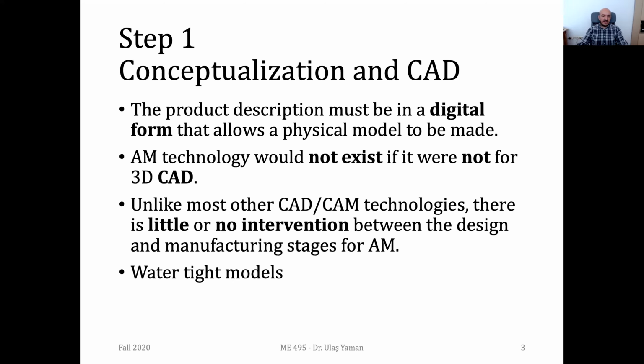And another important issue in terms of CAD software is that we need to have watertight models while designing our parts. Otherwise, once you do the conversions into STL files or different mesh file formats, you will have problems in the slicing. And once you have these problems, you can use some STL fixing software like NetFab or Meshmixer. There are such STL fixing software, but if your CAD software is powerful, then the result of your conversion should be a watertight model.